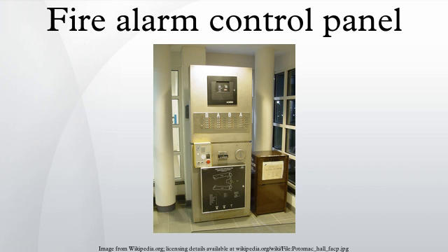In a trouble condition, the panel displays the zone or devices causing the condition. Usually, the trouble indicator goes out automatically when the situation causing the trouble condition is rectified. However, in some systems the panel must be reset to clear the trouble alarm. Some panels have more specific indicators such as trouble PSU, which shows when the panel itself is compromised, and trouble bell, which shows that the sounders are not functioning correctly. On most panels, an acknowledge button is pressed to turn off the panel's buzzer.